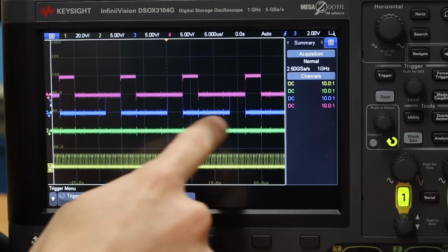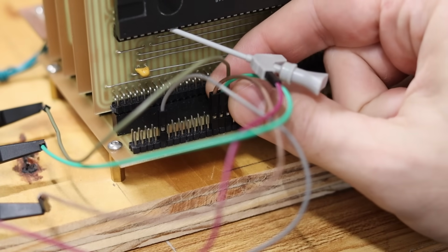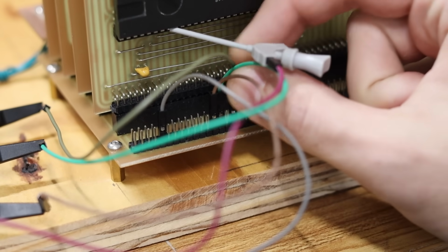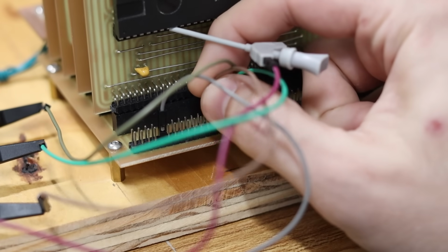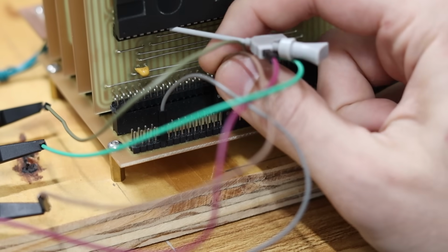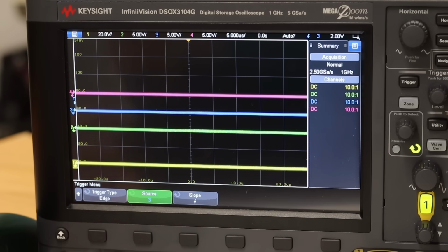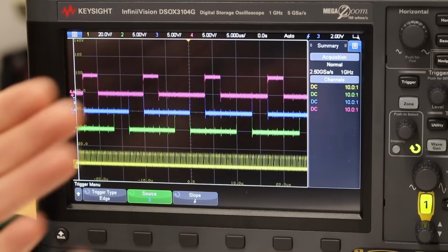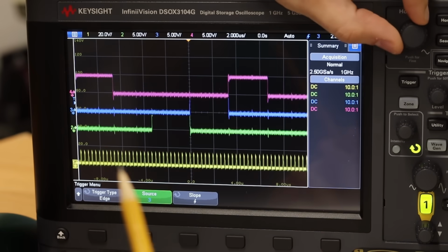So the question is why is this memory address line not toggling? Yeah, looks like I counted incorrectly here. I think I'm off by 1 pin. So we're going to scoot all of these down by 1 here. All right. There we go. That should now do what we're expecting it to do. And here we go. Power coming up.